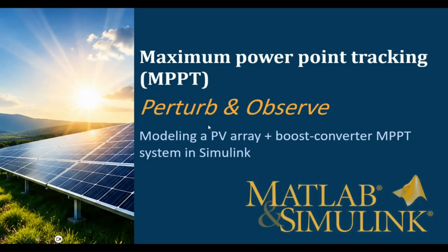In this video, I'll explain how to model a photovoltaic, or PV, array together with a boost converter and a maximum power point tracking system using MATLAB Simulink. We'll begin with the basic operating principles of solar panels, then study the Perturb and Observe algorithm, also known as PNO, before moving on to PI control and PWM generation. By the end of this lecture, you'll understand both the electrical system and the complete control strategy behind an intelligent PV energy conversion system.